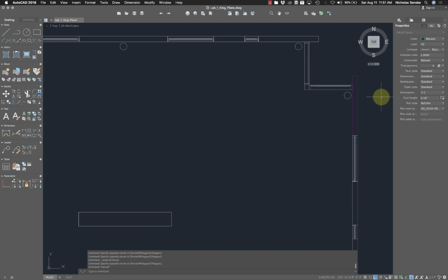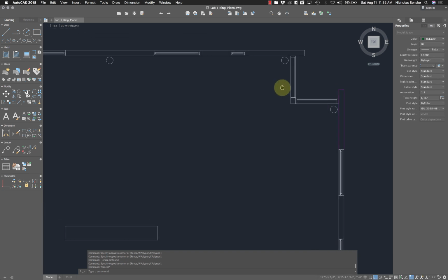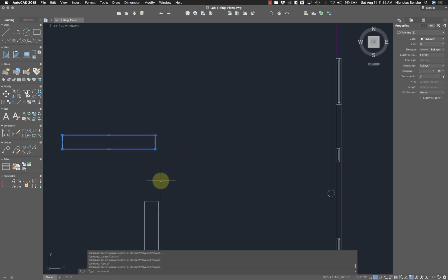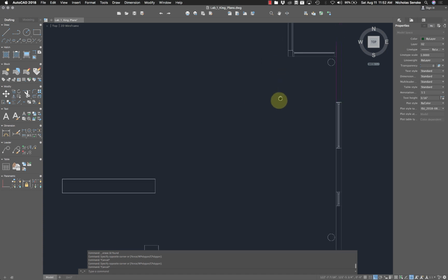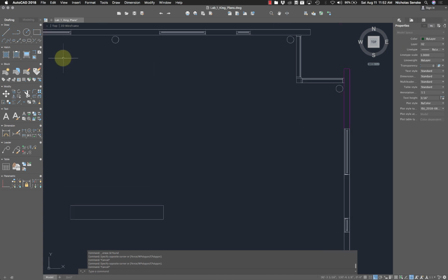But you need to be thinking about that in reference to the other drawing that we showed you, and which colors and which line weights were used to define which kinds of objects. You want to think about how the drawing reads spatially, like what is thick, or what is important, and what is less important. So the walls, obviously, are going to be critical. The structure, the columns, the windows will be there, but they're less important. And then the furniture, and so on and so forth. You might think about furniture that's permanent, such as these lockers, versus furniture that can be moved, like your tables and chairs. So anyway, line tool.